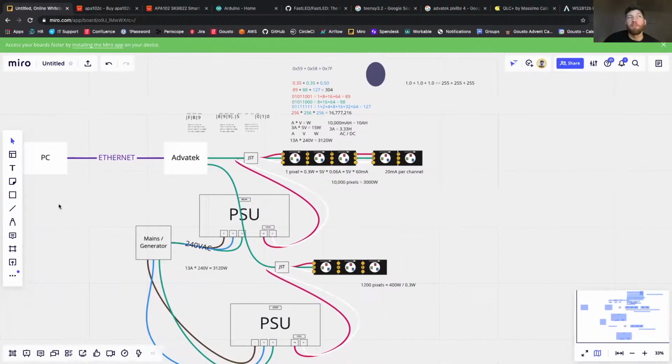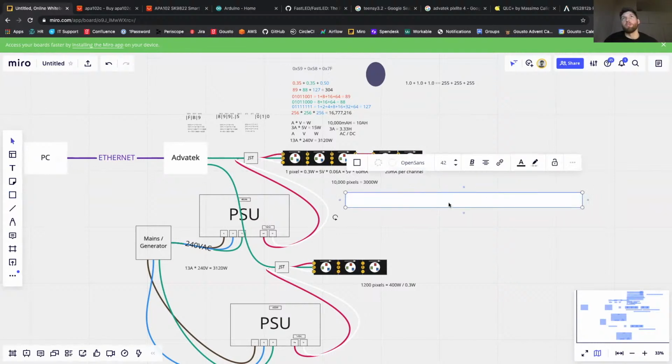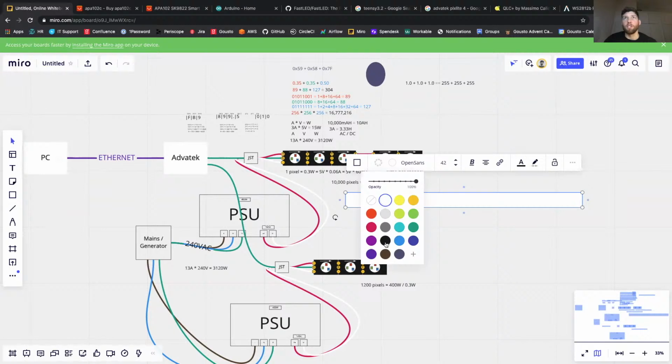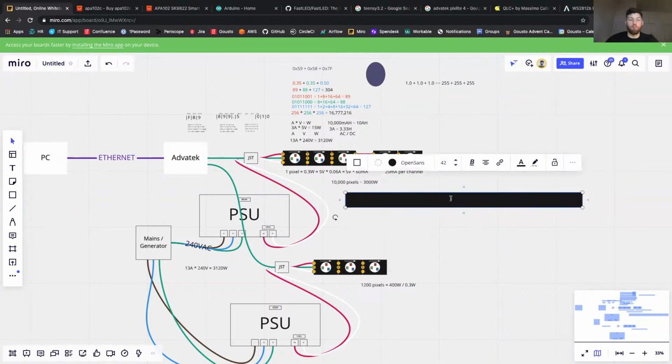I've seen some success with using drying silicon caulk, like you would use for bathroom tiles, to adhere pixel strips to a substructure. But ultimately, you're going to want some sort of bar or beam or wood plank or aluminum channel to adhere these things to. Let's just make that loud and clear.